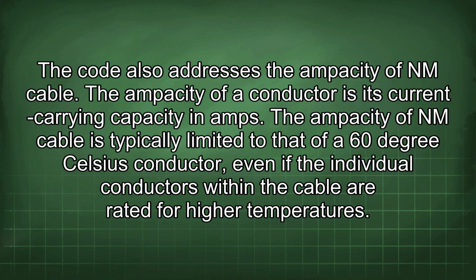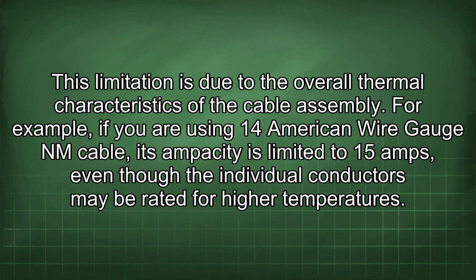The ampacity of NM cable is typically limited to that of a 60°C conductor, even if the individual conductors within the cable are rated for higher temperatures. This limitation is due to the overall thermal characteristics of the cable assembly. For example, if you are using 14 American wire gauge NM cable, its ampacity is limited to 15 amps, even though the individual conductors may be rated for higher temperatures.